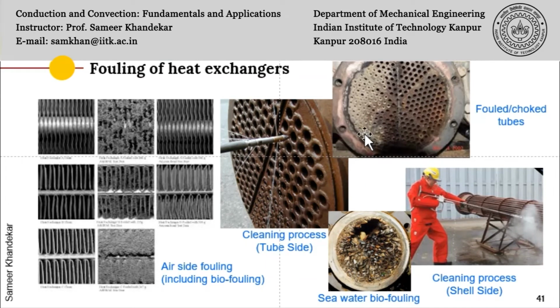Now the cleaning, as I have seen, see here you can see the shell side choked, on slide 41. You can see complete choking also because of seawater biofouling. So you can see a lot of animals, these crustaceans, trying to make their colony here inside the heat exchanger. And this can be very, very difficult and detrimental to the health of the whole plant. A power plant which is using marine water for cooling of the heat exchangers or cooling of the engines, for example, or turbines, the cleaning is usually quite an arduous task.